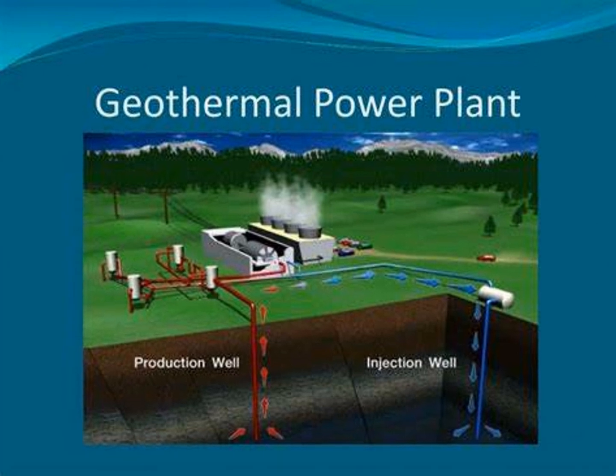So this is a typical picture of a geothermal power plant. This is the production well from where the steam is being collected. These are the separators where the steam is pressurized and then fed to the turbine. This turbine, when fed with this high pressure steam, starts rotating, and due to its rotation, the generator also rotates as it is connected with the shaft.